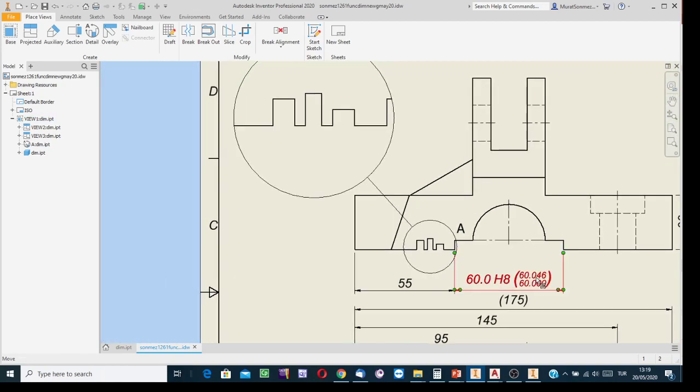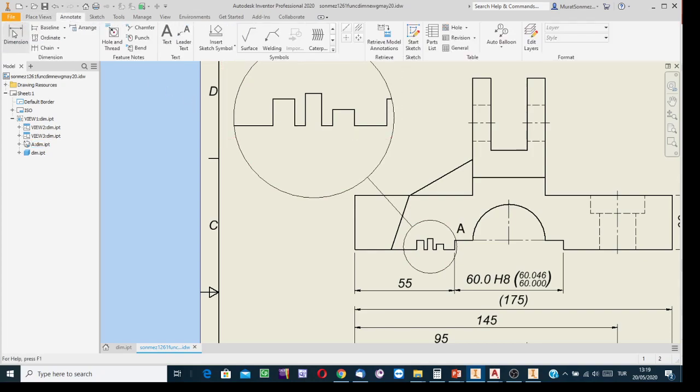And then on the detail view, show the dimensions. I make the projection large enough. I may show the dimensions using arrowheads, but if it is going to be chain dimensioning, it is more convenient to replace arrowheads with dots.